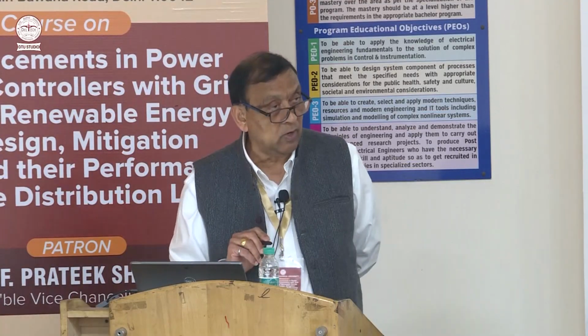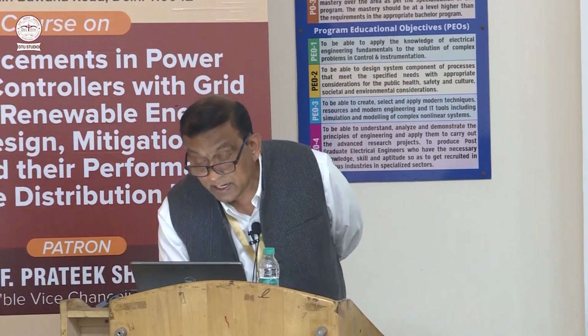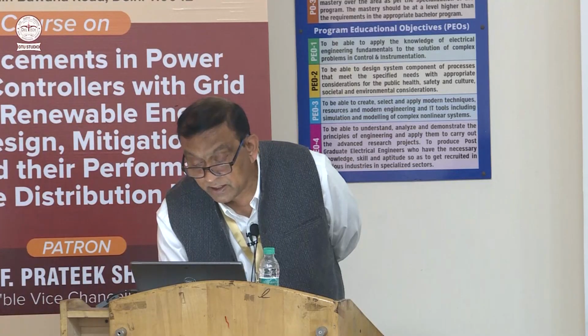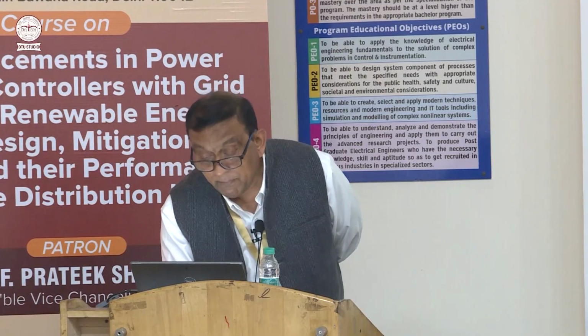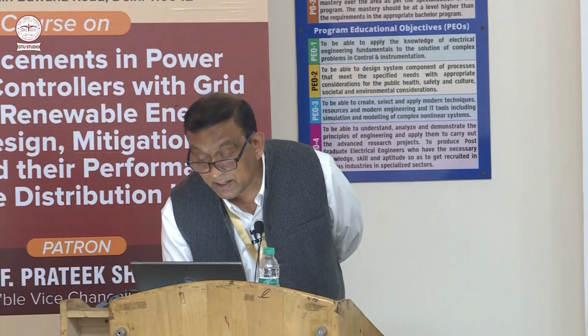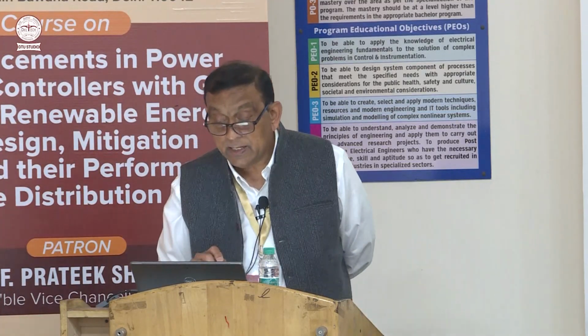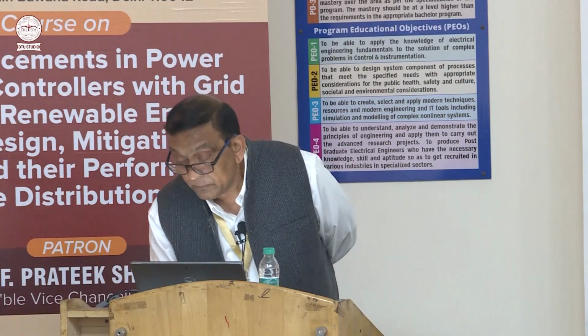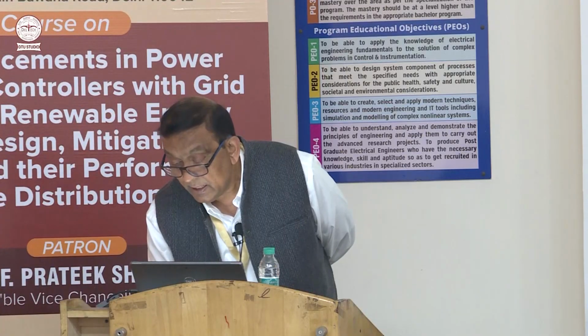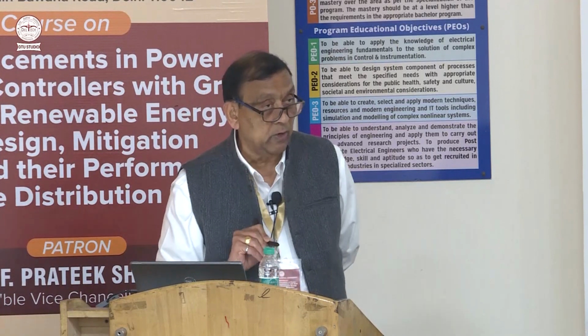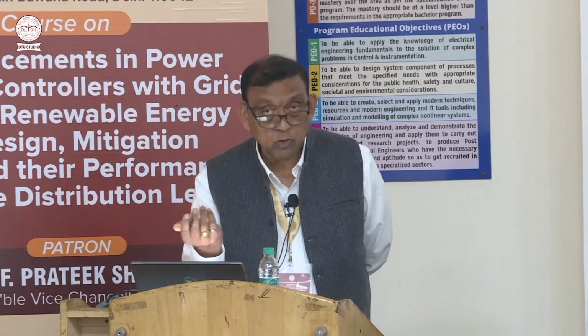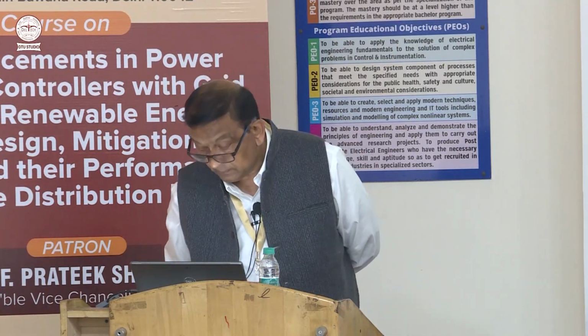So this is a polygon connection. And here also you can have the same thing, like 15-degree phase shift here. Depending on the number of turns in the primary, you can adjust the number of turns. The only difference, it is closed at delta, zigzag for higher voltage, polygon for lower voltage. But polygon is also very popular in applications.